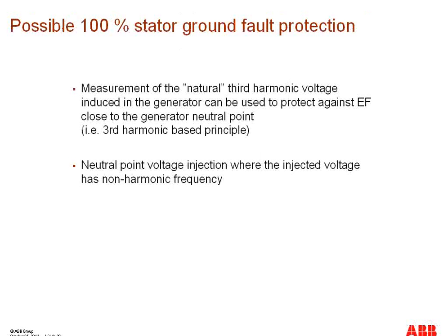So for 100% stator ground fault protection, normally there are two principal methods which are used to protect the 100% stator winding. And these methods are by detecting the third harmonic principle, as well as by the injection method.